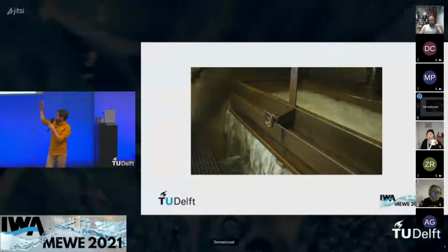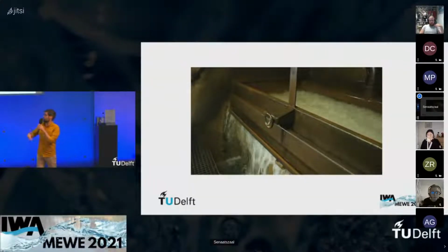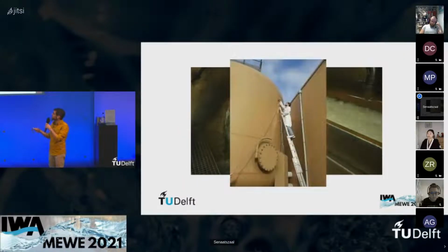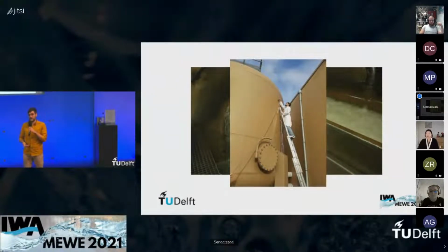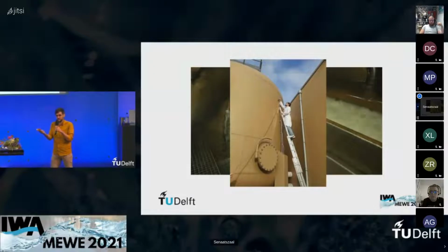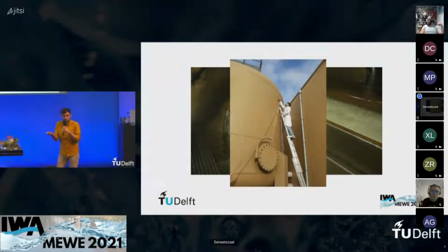The water flows from the top to the bottom, and air flows from the bottom to the top. So you reach saturation levels of oxygen. And then once the water is fully aerated, you send it to a dry sand filter, which is a huge tank full of sand grains. In the sand grains, with the oxygen, your contaminants are oxidized, they precipitate, and they're trapped within the filter, which yields clean drinking water. The problem is that all of this, which I explained very quickly, happens via many different reactions which also interact with each other. So when you try to understand how the filter works, you have a myriad of different reactions which are difficult to understand.